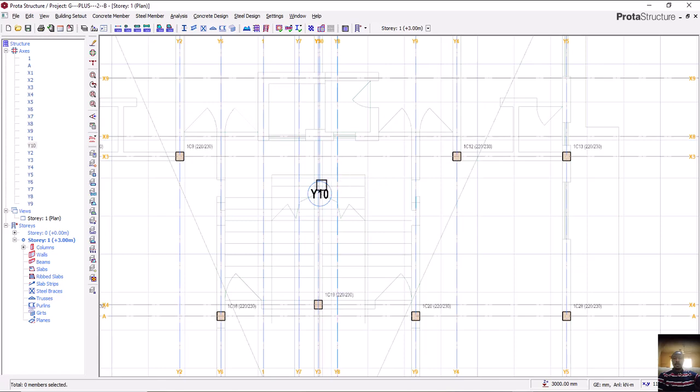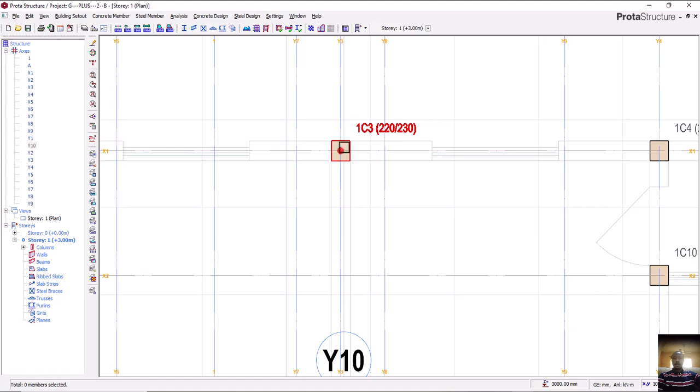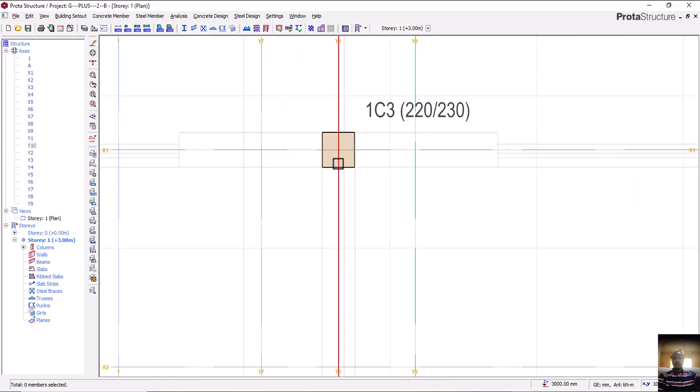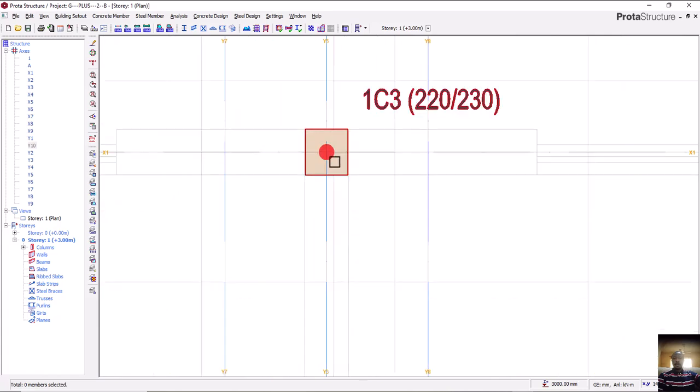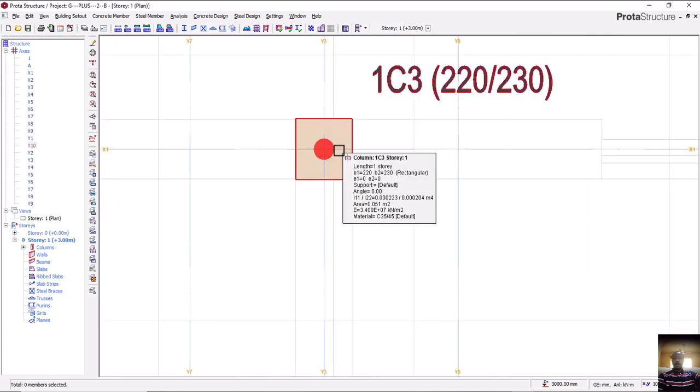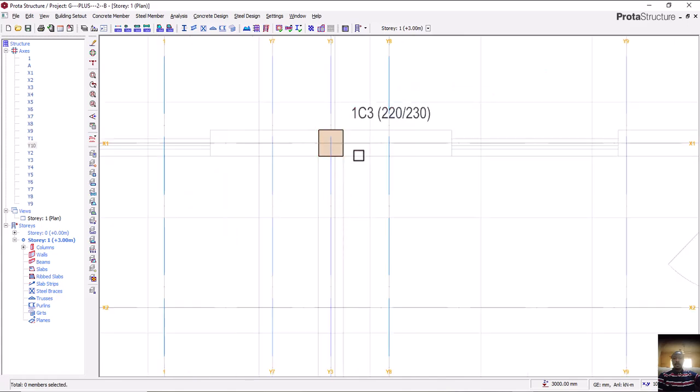Okay, fine. So the reason why I'm doing that is because if the axes are too close, it might want to create a beam in between them. Is that okay? That's another thing you need to know. If the axis is somewhere here, by the time I draw my beam and try to go to the next one here, it might want to create a beam between this one and this one. That's why I drag it down so that it will not do that. Is that okay? All right.